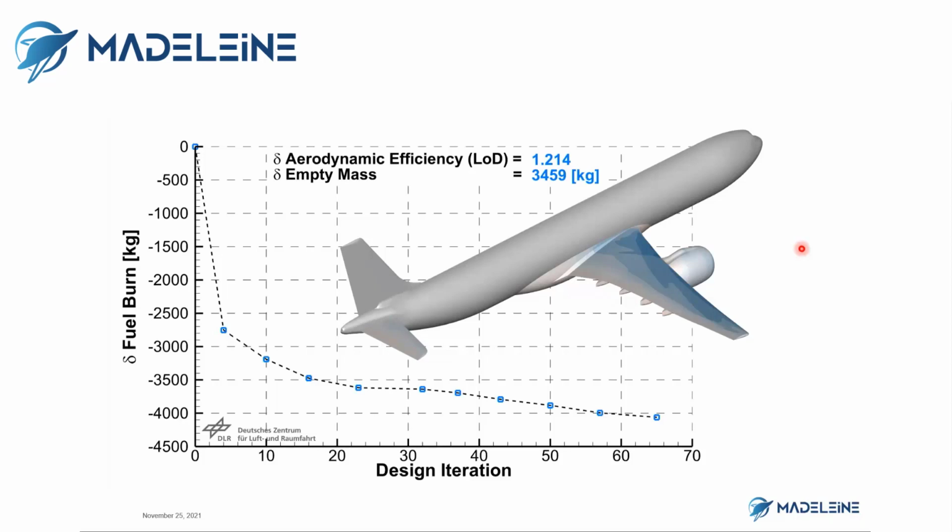So two questions from Stefan Gertz from DLR. From what I understand, Dassault, NTUA, Airbus, DLR, and Onera compare rigid and flexible optimization using coupled adjoint. Did you compare both approaches and aerostructure optimization? The purpose is not the same between aeroelastic optimization and aerostructural optimization. On aeroelastic optimization, the purpose is really to improve the drag performance.